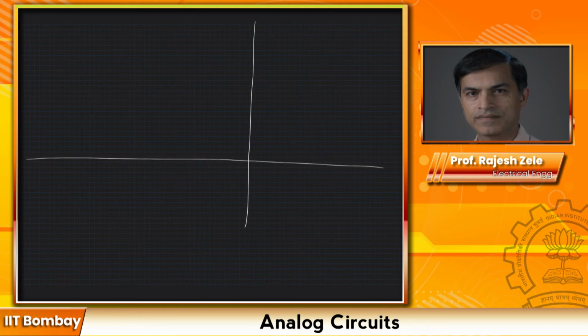Okay, so what I am showing is something like this, and originally I showed you that, hey, the current is really small, close to zero, like this, and this is our voltage V and this is our current I. So in this case we are assuming that I can apply negative voltage or reverse bias potential for the diode as much as I can, but in reality that is not possible.